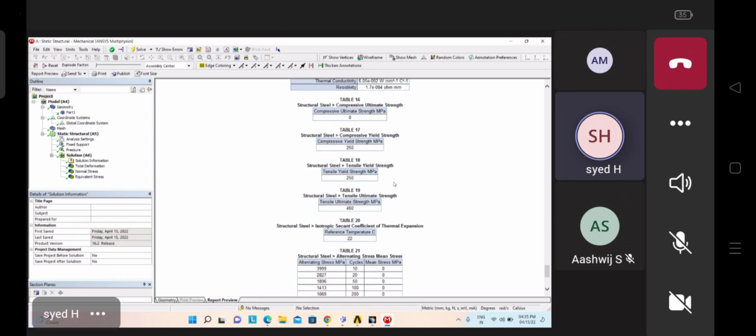Usually pressure will not get reduced. Why? Because we are considering that much pressure only, we require that much pressure. When we are creating any component, first of all we think how much load it is getting there. First thing we check that one. So anyhow we require 1200 psi pressure, definitely we require that. So we cannot change the pressure. The only thing we can change is our model.